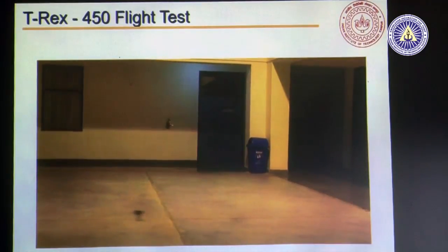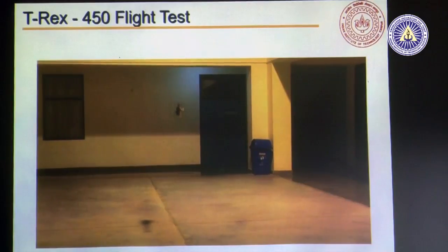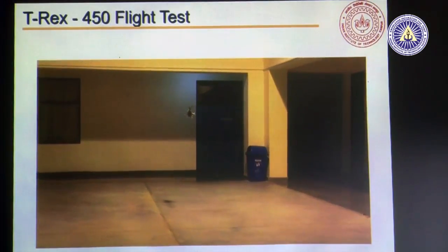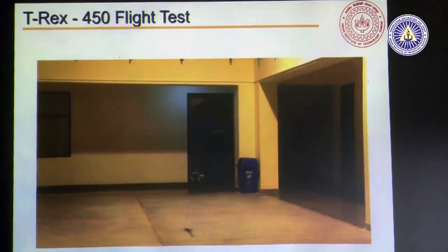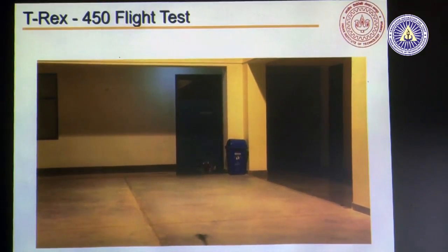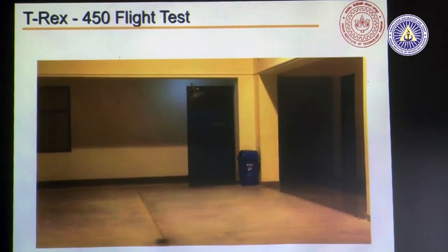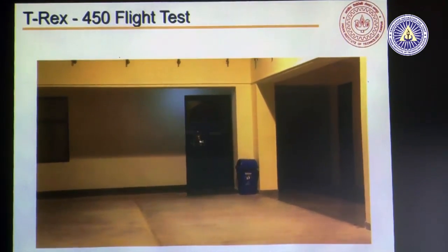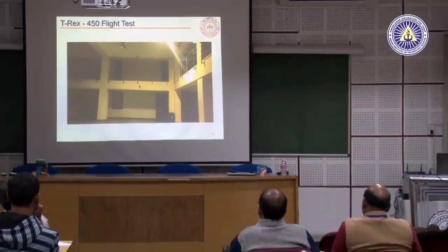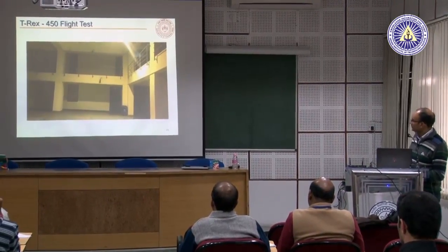Now it is getting very small inputs, but at very high frequency. Now you are only giving that input, so it will start losing thrust and it will start coming down also. So you have to be aware of that. Normally, for big helicopters, these kinds of experiments are done at much higher altitude, so you do not have to worry about the helicopter coming and hitting the ground. Now this is giving pitch input, so you can see the continuous pitching motion being given.